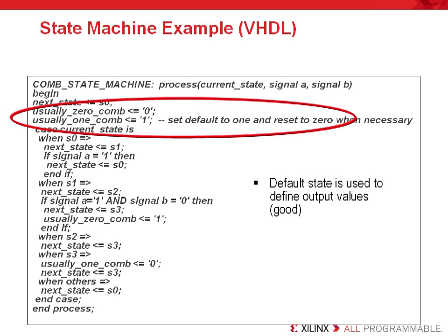This is not recommended since most finite state machines are larger than this one and more complex, and they would get better speed by separating out the outputs from the next state logic. You should also note that this finite state machine defines a default output value. This simplifies the logic generated and is a recommended practice.